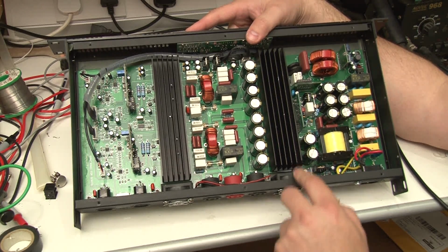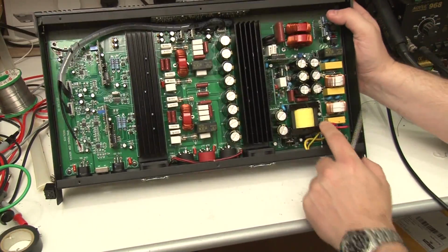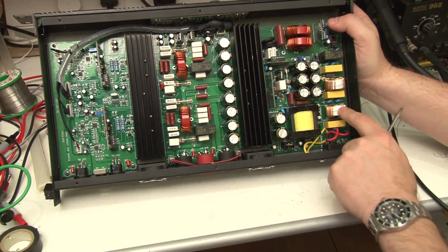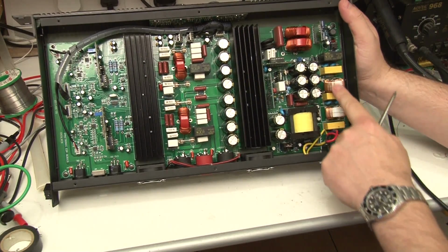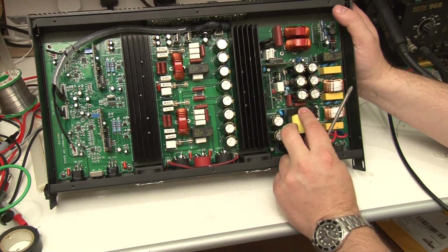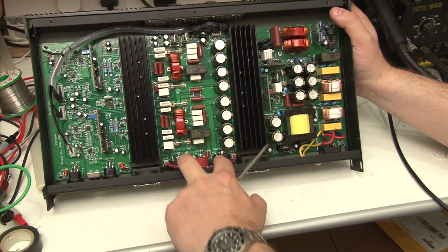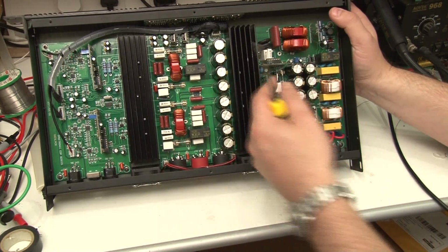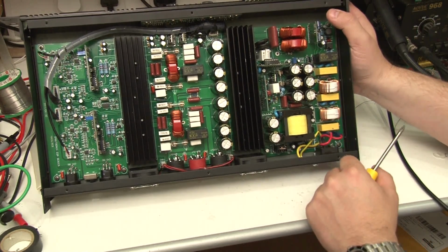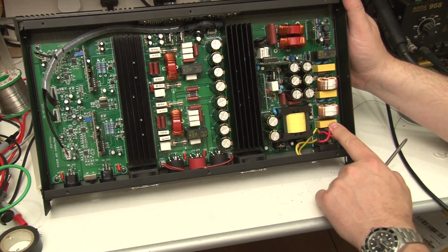Rather counterintuitively, I don't believe that's channel 1 and channel 2, and we'll just run through that now and see what we've got. So mains input here, off an IEC connector, straight onto the board, and this is very traditional mains filtering. The filtering here is quite important, because all of the high frequency switching of the switch mode power supply is filtered out, getting to the outputs. But there's plenty of room for it to come back this way, and from a regulations point of view, you don't want to be putting noise back out into the mains. So that's quite important. I suspect there's power factor correction in this switch mode as well.